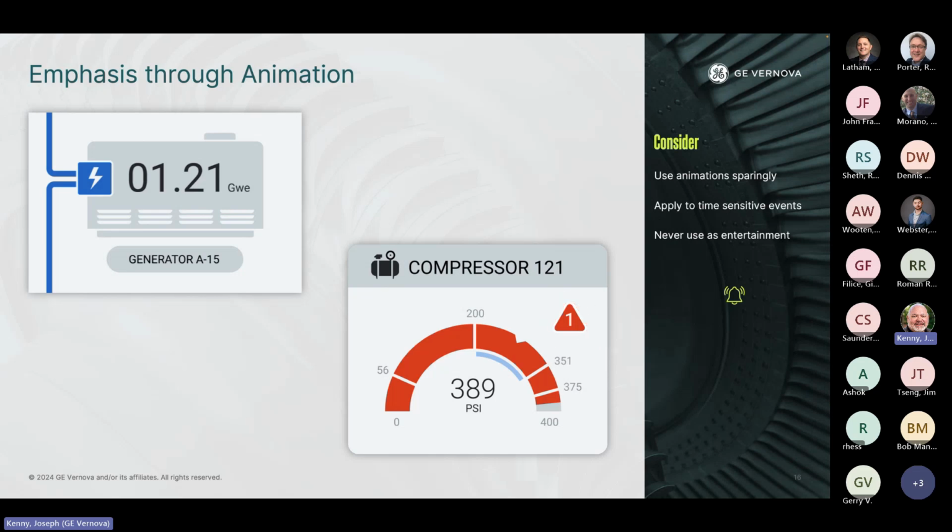It's actually flashing now and showing the alarm. So it's containing all kinds of information through the animation. It's showing me where I'm in range, where I'm out of range, when I creep into a different state, and changes color and the symbol as I go into a more critical state. And so using animation that way is the best way, because it's actually valuable information that helps the operator offset an issue like this and maybe prevent it from getting to that red state.